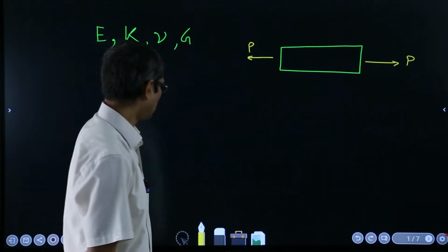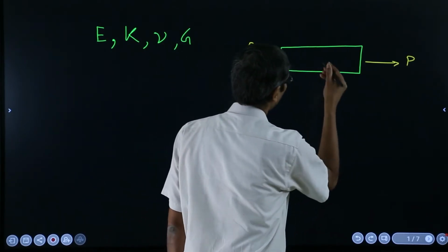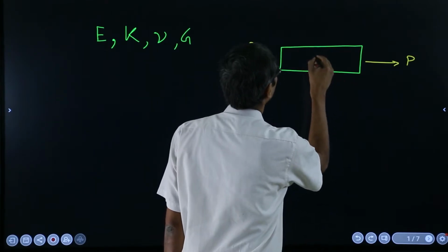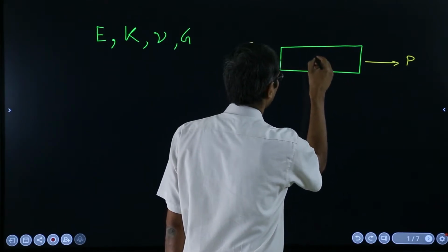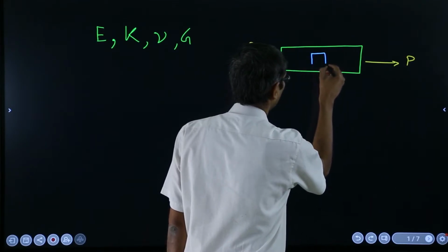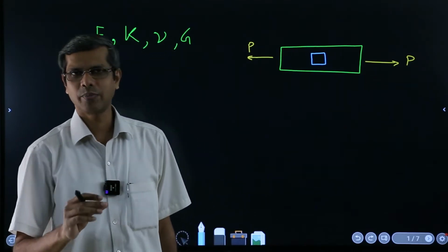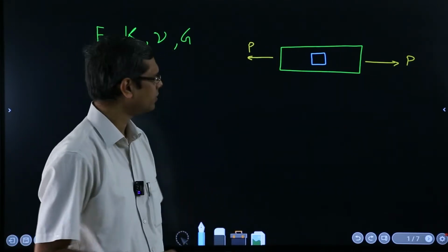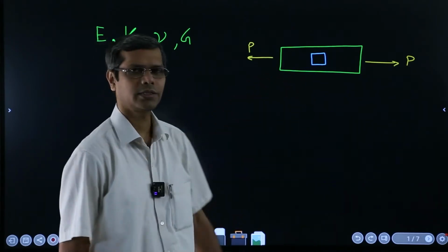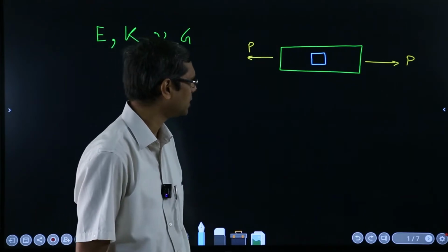And then what we do is we will look for the state of stress at a point somewhere on the body, and in order to do that generally we draw or we imagine picking an elemental square, right, for plane stress condition. And in this case obviously in the z direction we are not applying anything, so there will be no stress in that sense.